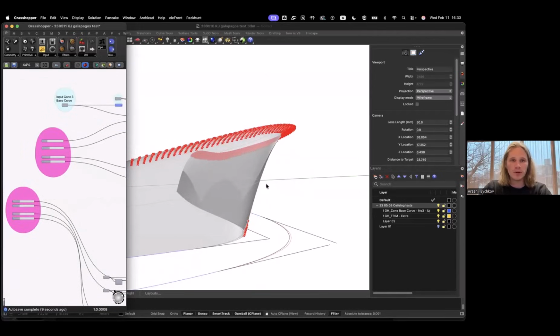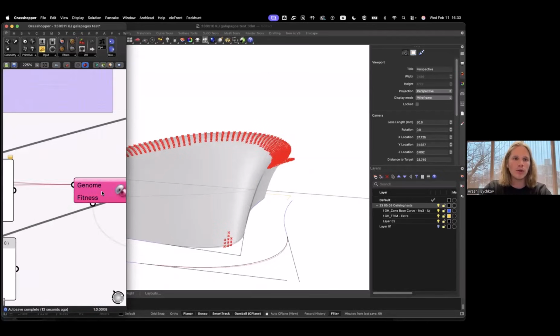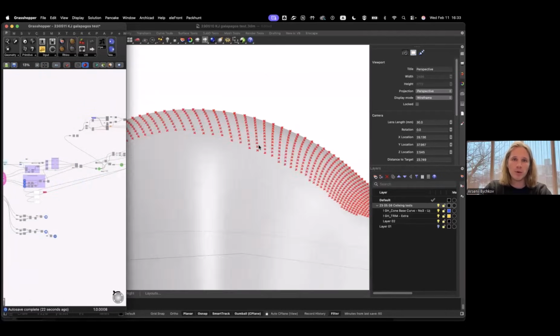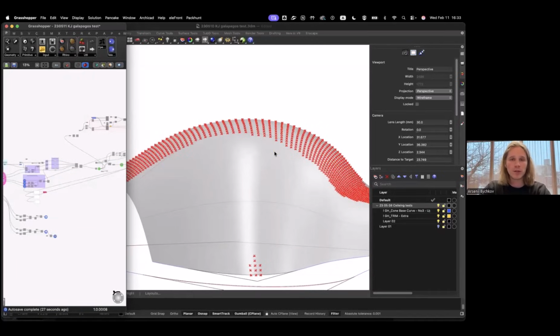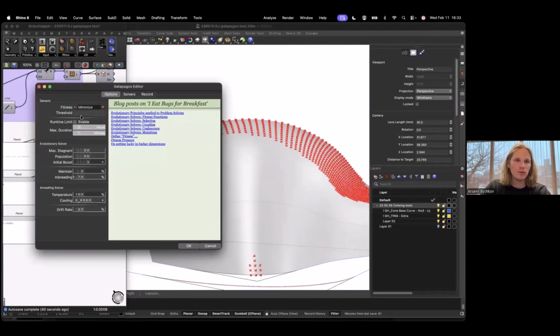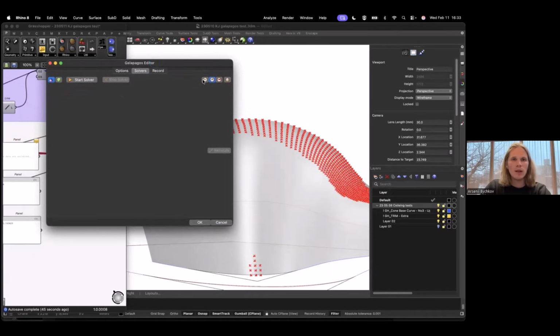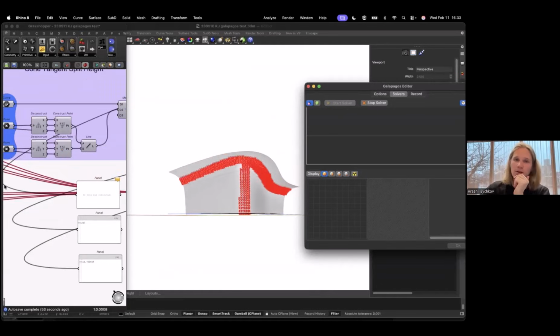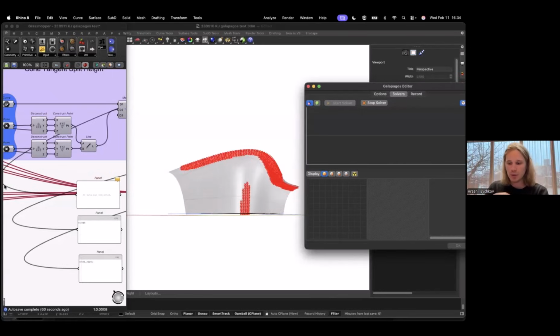These parameters that were defining how the surface of the cone looked were used as a genome for the Galapagos tool. As a fitness function, we used the amount of points with the minimum critical curvature, which was 2 meters. We couldn't go less than 2 meters, and if the curvature was lower than 2 meters, we had to readjust the script. Here I'll quickly show how it works. I'll put a 1 minute runtime limit. It quickly checked the different parameters and different shapes of the surface of this cone, creating different combinations of these parameters to find the optimum scenario where we have the minimum amount of small curvature points.